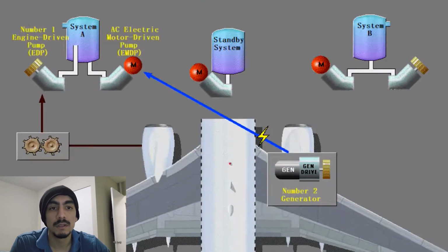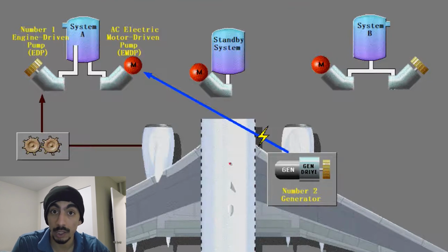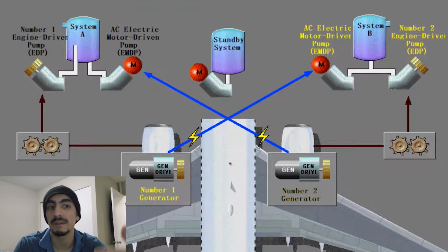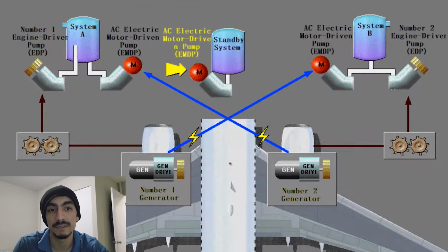When the pilot moves a control column or flips a switch to, let's say, deploy the landing gear, the valves open up in the hydraulic lines, and the high pressure fluid pushes the pistons and the actuators to physically move those parts. In other words, the pilot's input tells the fluid, go here, apply force there, and that's how the airplane's big, heavy surfaces actually move in real time.